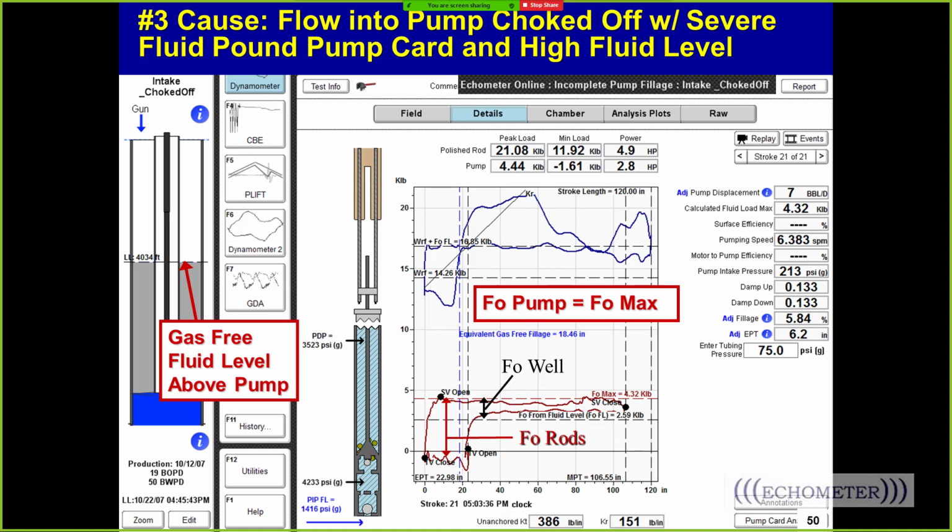I have one more question, which I'm not sure is totally clear. If I have a low pump submergence, would you recommend increasing the casing pressure to have better pump fillage? If your pump fillage is low, then you're pumped off. That means your pump exceeds the inflow and your pump's not full.